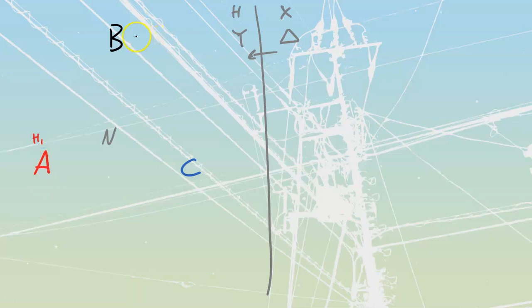H1, H1, and H1. All of those lines are connected in. Now we can make the connection. We're looking to create a Y type of connection, so we're going to be bringing everything over to the neutral. A phase comes into the neutral over there. B phase comes into the neutral over there. C phase comes into the neutral. Remember that we are going to be creating this neutral, which means that we're also going to have to ground it.